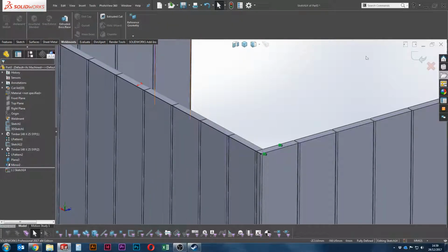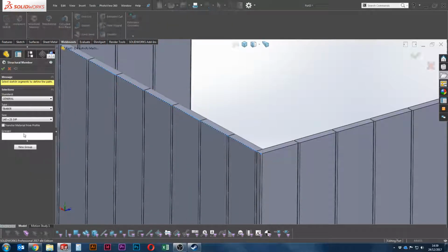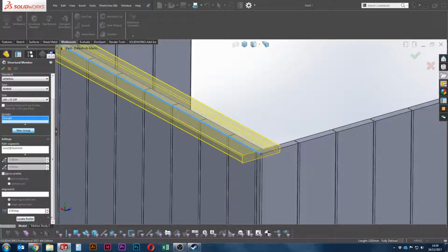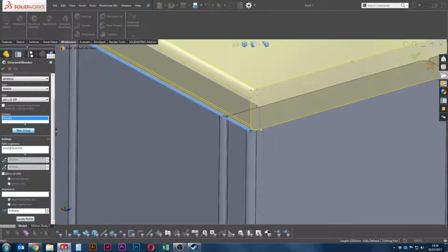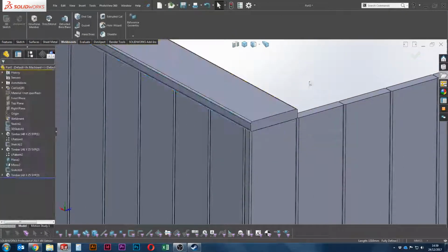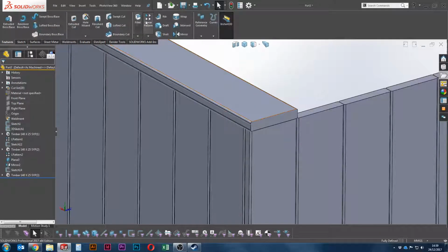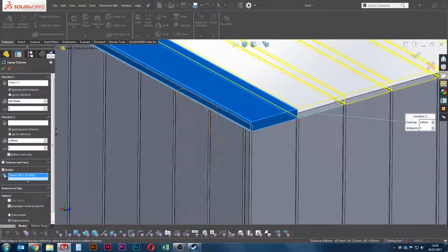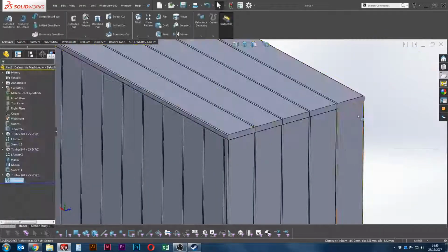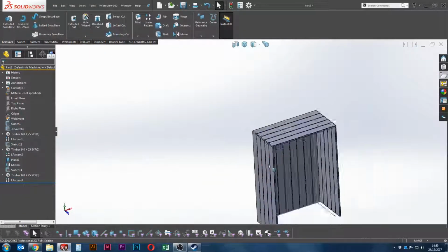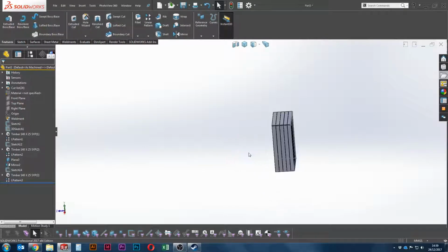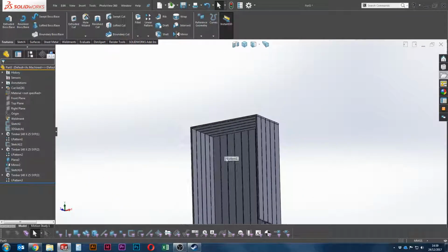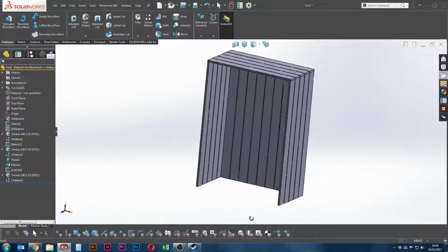And then click on Weldments again after exiting the sketch. Click on that, click on that line, locate the profile again, and then select the bottom left so it sits on the top. Okay, happy with that. Linear pattern, select that edge, select that body, and we've got our top there. So we've got a nice little kind of hut, which is perfect. That's all we want to see.